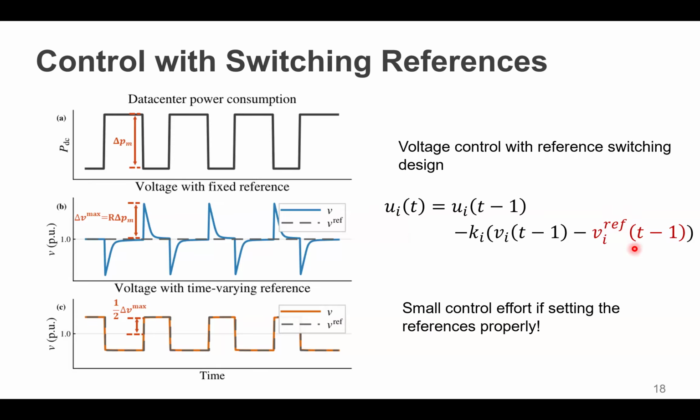So are you saying, I am trying to understand, are you saying because the load changes so fast, I have to change the reference point and my voltage at the same rate? They will fight each other. I mean, I set the reference point and right away I want to be there, and how can that work from a control point of view? All right. Because the reference point is essentially 1 step later, the key point is that the voltage reference. How big is the step?